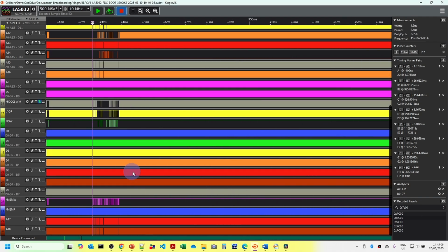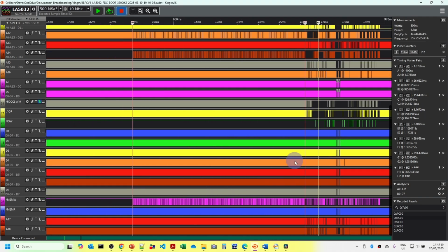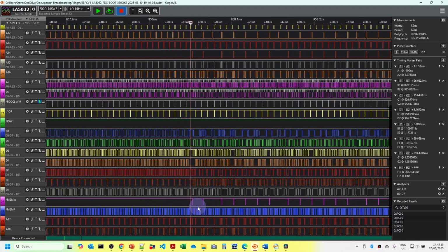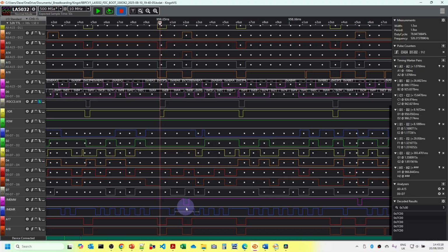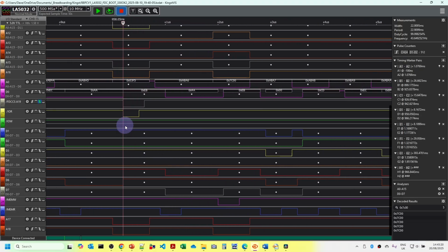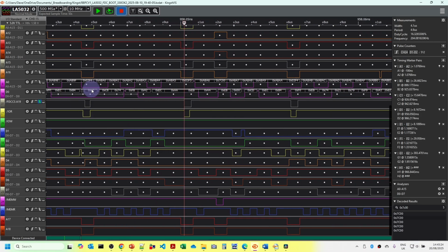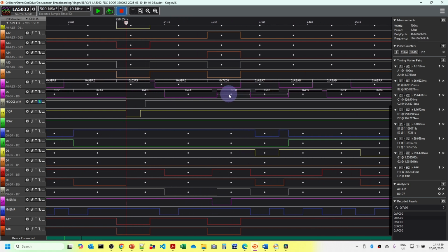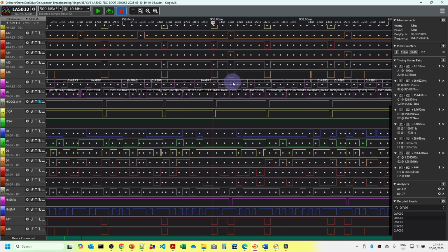Then we actually do the read. And what we can see here is the output of the data from the read. We've sent a read command, and you can see that we're receiving a status to say that there's data ready. We're reading from the data port the value of EB. Now, if you remember, EB was the first data of the boot sector. And just here, we're then writing EB to 7C00. So this is the first byte of the boot sector.